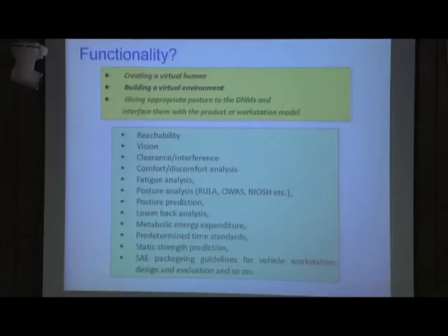Those include reach analysis, vision analysis, clearance interference study, comfort discomfort analysis, fatigue analysis, various types of postural analysis using various types of postural tools like RULA, REBA, OWAS, NIOSH, etc. Then posture prediction based on preset criteria, lower back analysis, spinal compression forces, shearing forces we can analyze. Not only that, even metabolic energy expenditure, predetermined time standard, static strength prediction, various types of packaging guidelines as per Society of Automotive Engineers or any other standard organization, as per their requirement we can also analyze our product or workstation.